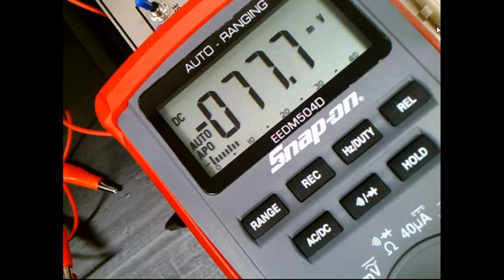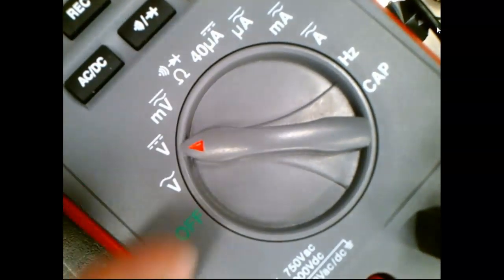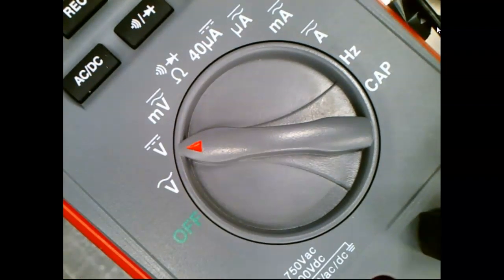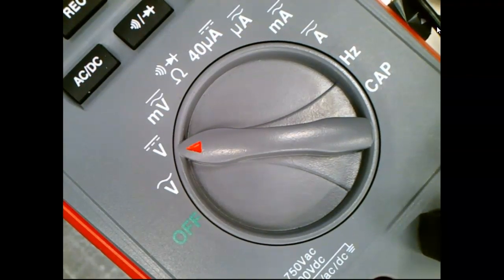So this is why it's important for you to know that if you're in an AC circuit, double check your meter to make sure it's on AC. Some of these meters use the same scale. This one doesn't, luckily. Well, we have some meters that use exactly the same scale, and you have to remember to push a button. I'm trying to figure out where my other meter is. Here, that's the meter here, and it's got one scale for both. You have to remember to push a button.